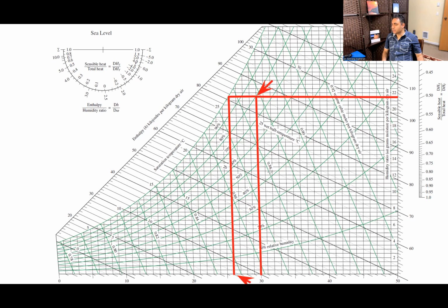That's very interesting. And we can write down these values, basically the average values that we want. On one note, I'm going to show you the values I got from the psychrometric chart. You can even pause this part of the video, go over it, and practice. If you want to practice, you can go to any thermodynamics book. All you need to know is that this is where we are right now. This is our point, and you pinpoint this location and from here you find everything else using the psychrometric chart.